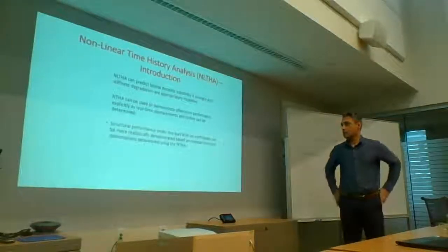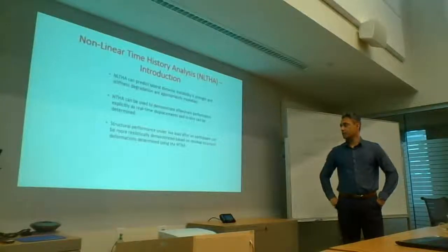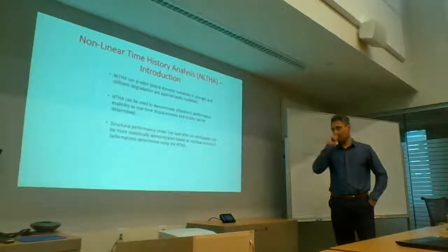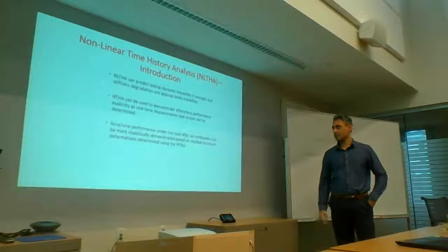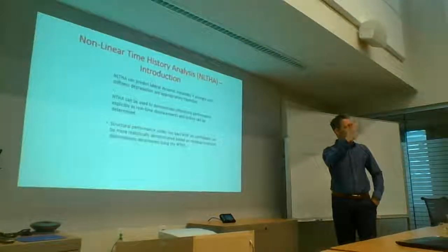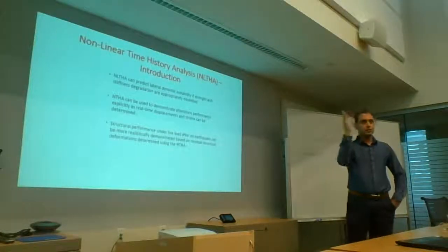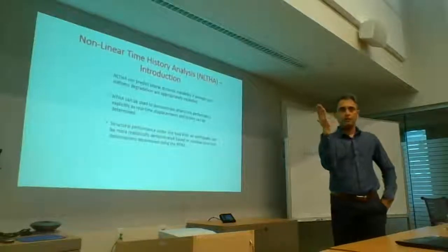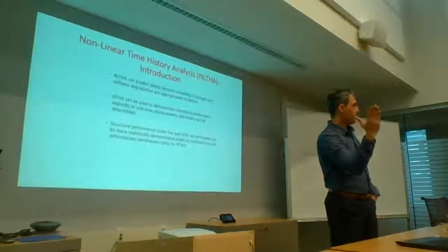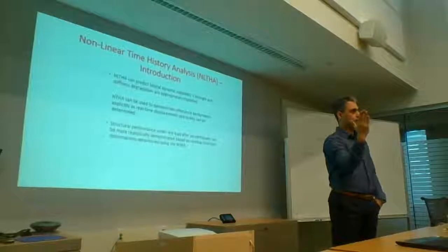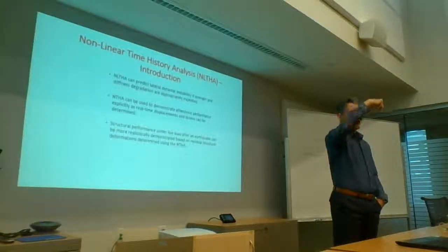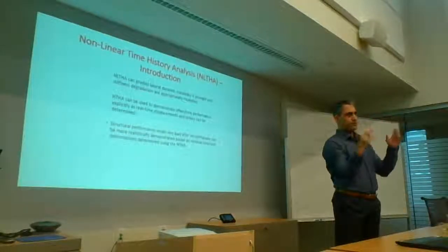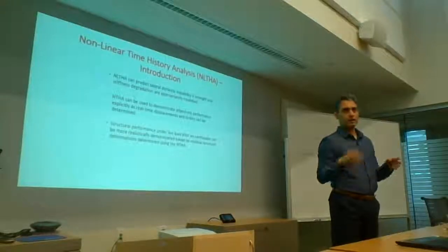Again, structural performance under live load after an earthquake. I touched upon this a little bit. It can be more realistically demonstrated. So if you run your time history and you put a bunch of zeros, you can figure out the residual displacement or drift after the end of the earthquake. Now you can put your traffic on it because it will have the drift, it will have those moments locked in.